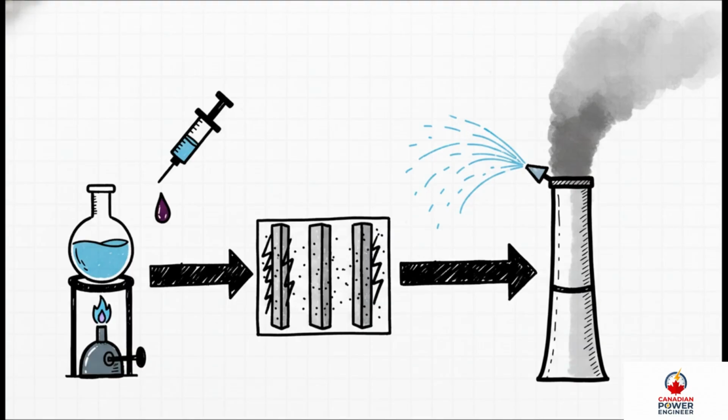By adding specific chemicals directly into the flue gas, we can drastically boost the collection efficiency of the equipment we already have. For instance, operators might actually burn molten sulfur on purpose to create SO2, run it through a converter to make SO3, and then shoot that into the ductwork. The SO3 alters the electrical properties of the fly ash, making it way easier for the electrostatic precipitator to grab.